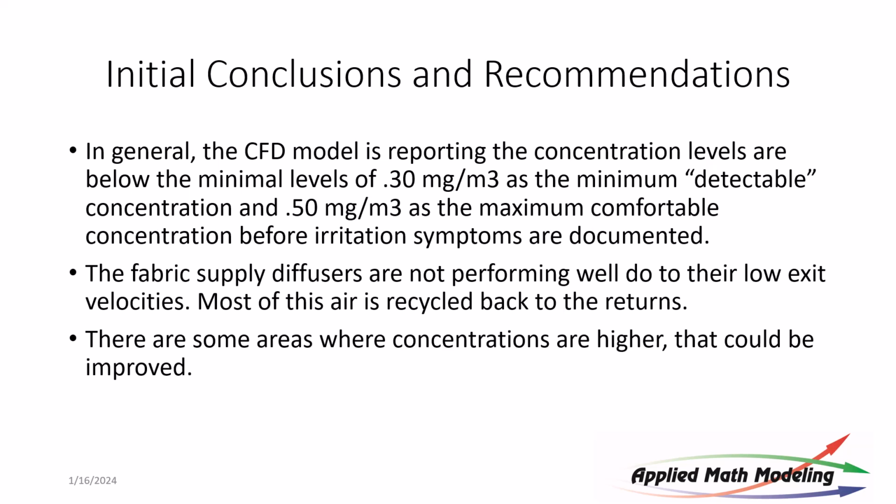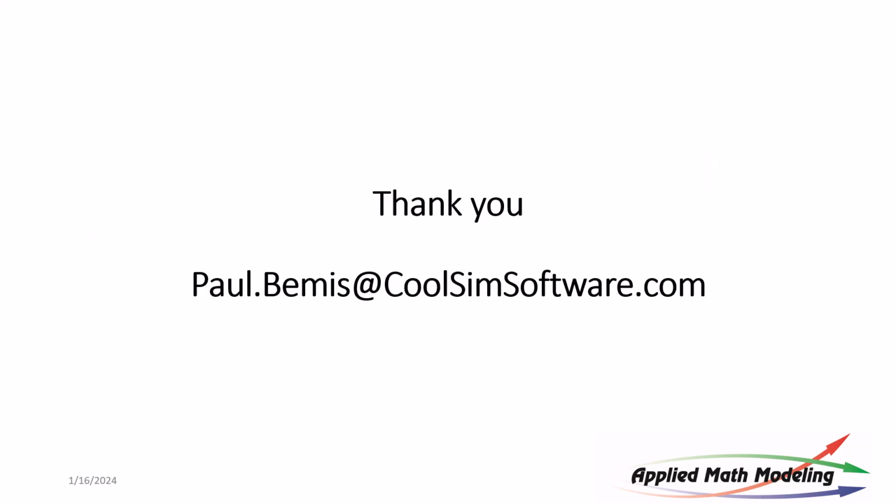In this case, they were fine. They were well below the 0.3 mark, so we were able to confirm that their design was quite good. We also made recommendations about the fabric diffusers not being ideal due to the low exit velocities. And there are some areas where concentrations were higher, but it could be improved, and the design team went ahead and did that. So that's a good example of using CFD in an indoor water park application to look at the effects of chloramine gas in the atmosphere.